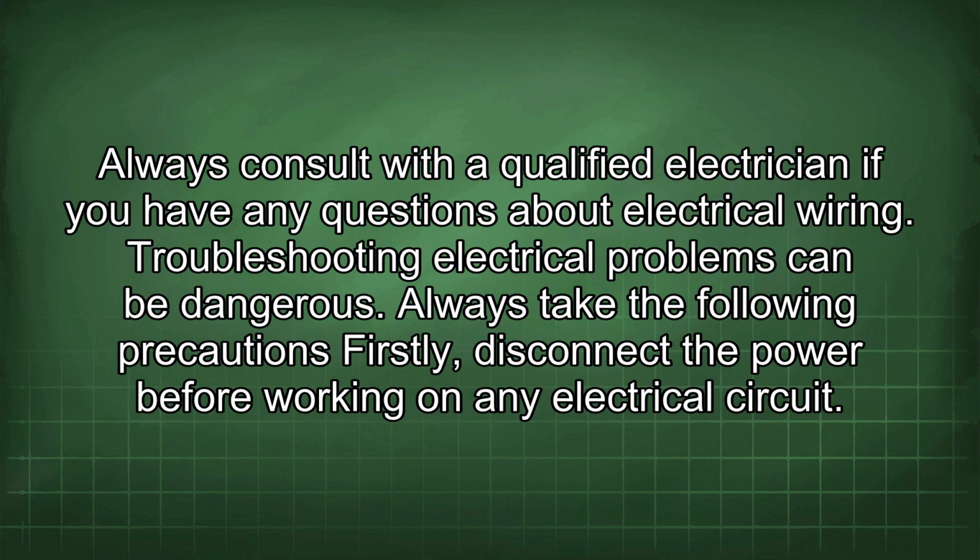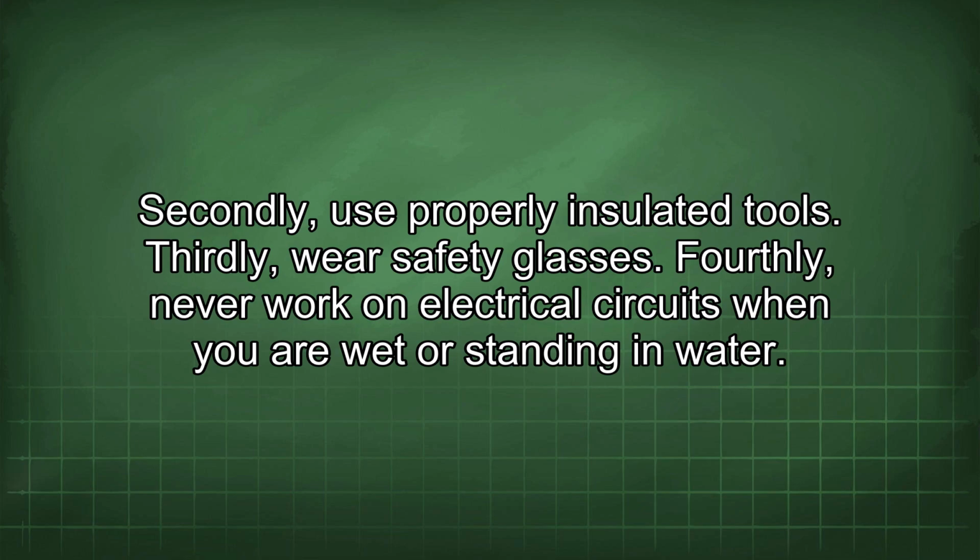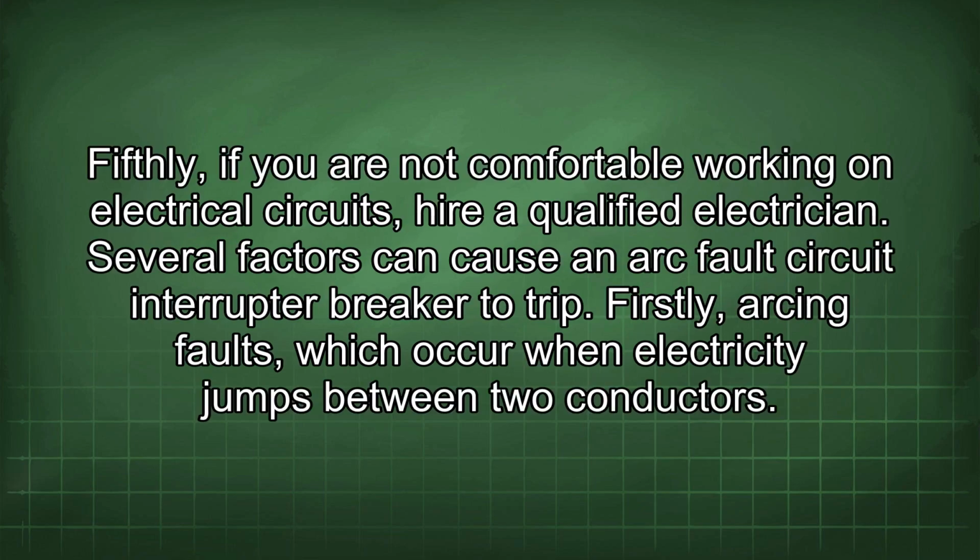Troubleshooting electrical problems can be dangerous. Always take the following precautions. Firstly, disconnect the power before working on any electrical circuit. Secondly, use properly insulated tools. Thirdly, wear safety glasses. Fourthly, never work on electrical circuits when you are wet or standing in water. Fifthly, if you are not comfortable working on electrical circuits, hire a qualified electrician.